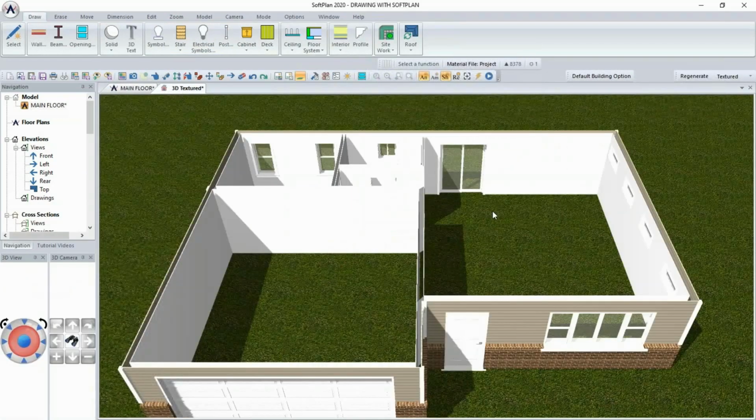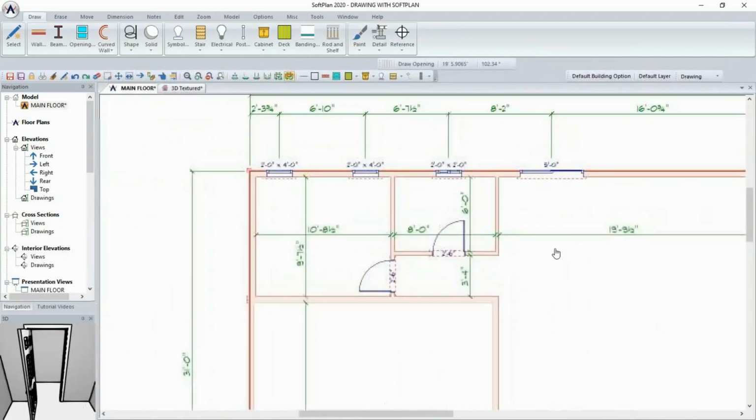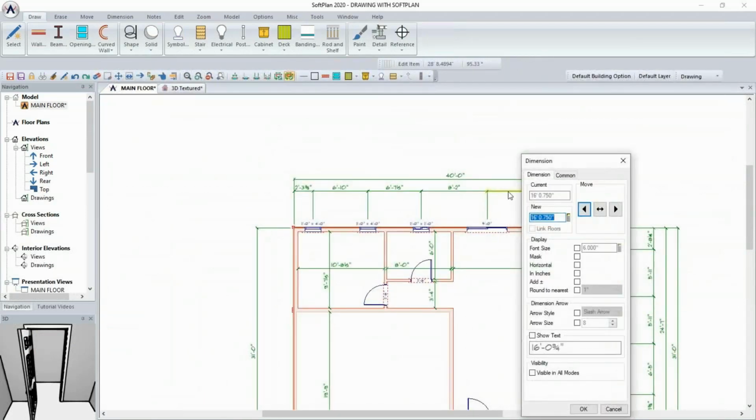Back in 3D, we now have our structure with all the openings put in place. Next task then is to position those openings. Now that they're all in place, I want to get them in the right location. I'll first start by modifying the dimensions. Again, like anything else, click on the side of the dimension we want to modify, enter twice.